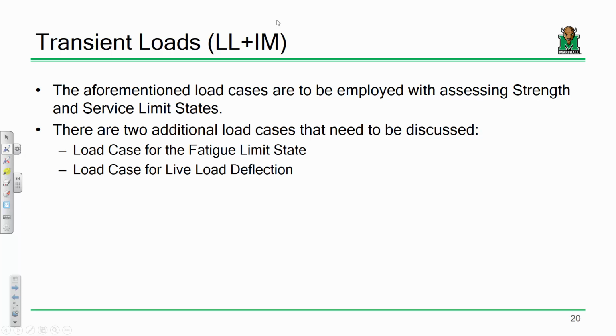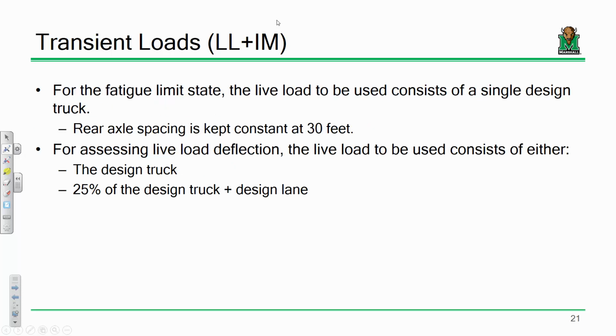Okay. Now, those truck loadings are going to be employed when you assess strength and service. When you do fatigue and when you do live load deflection, you do something a little different. For fatigue, this is what I was mentioning earlier. You use the truck, but you use the truck where the rear axle is affixed at a constant distance of 30 feet.